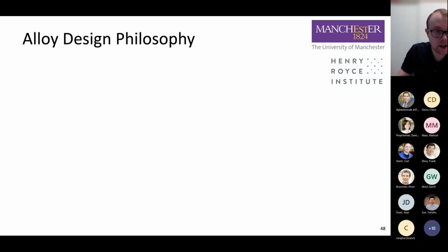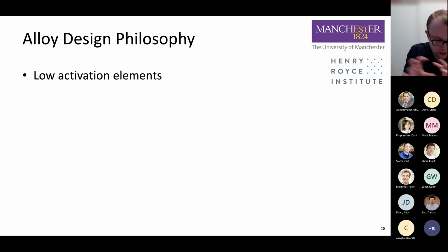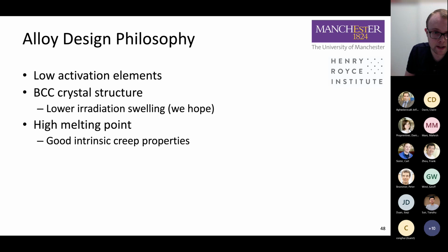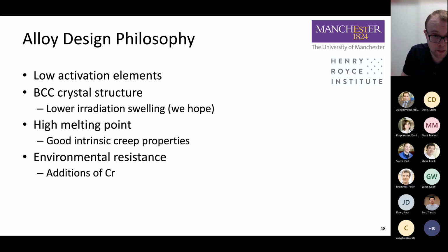The design philosophy that some of my students have adopted follows on from what we just discussed about face-centered cubic and body-centered cubic high-entropy alloys. We've used low activation elements. We've looked at body-centered cubic crystal structures, hopefully, so this means that we get lower radiation swelling. We've looked at high melting point elements for good intrinsic creep properties.